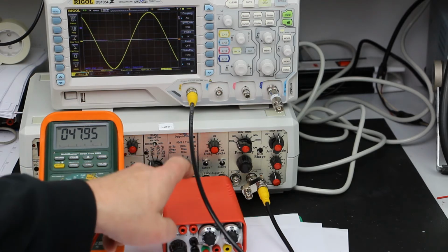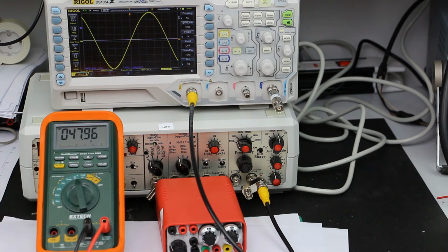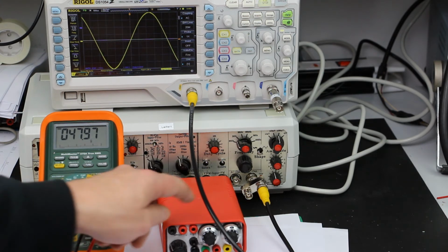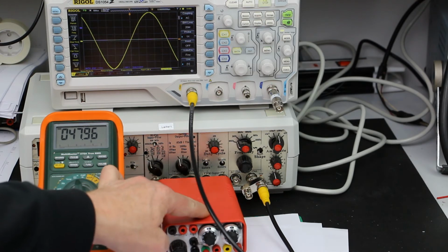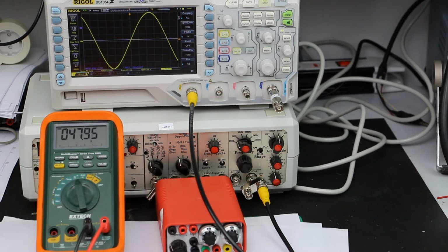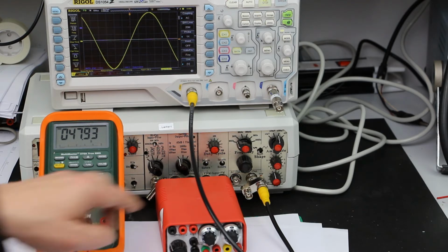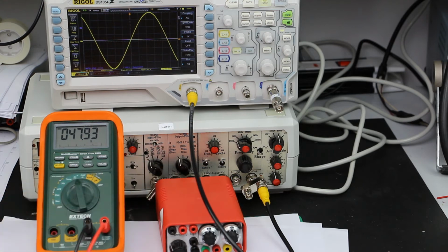But you should never do this with a power supply or with a power amplifier, because then there's the danger that the resistor you are using for making this check starts to heat up and even burn in the end. So you should, of course, be aware of the output impedance you expect from your source.